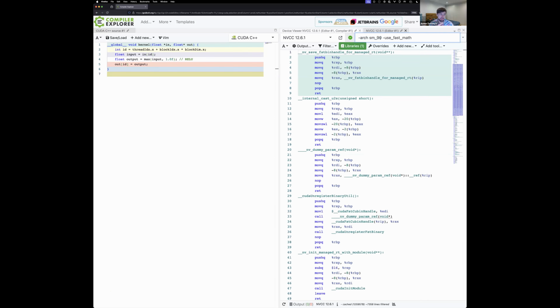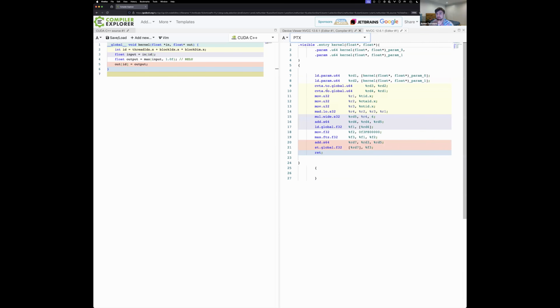I think something that's really important to realize is that PTX is forward compatible. So for nearly without exception, as far as I know, you could run even G80 PTX on Hopper. However, there are new PTX instructions that get added over time. And those PTX instructions may allow the compiler to use some hardware instructions that otherwise would effectively be emulated.